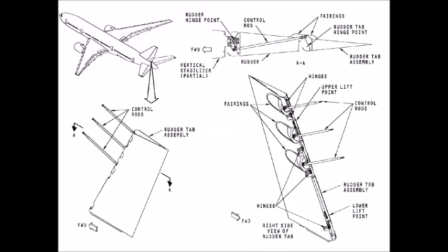The rudder assembly purpose is to supply the control of the airplane in the yaw direction. The rudder tab pivots on the lower trailing edge of the rudder. The rudder is a lightweight composite material structure. The skin is reinforced graphite bonded to a core of Nomex honeycomb.